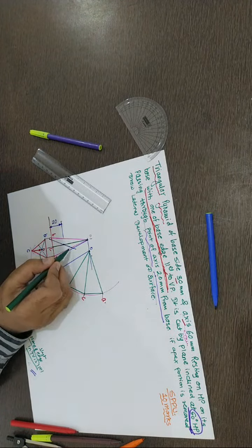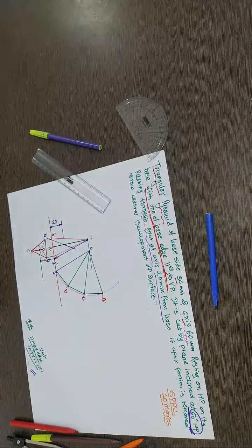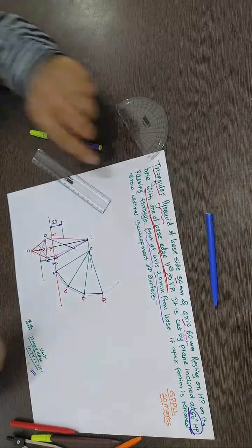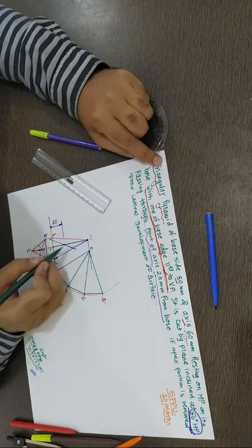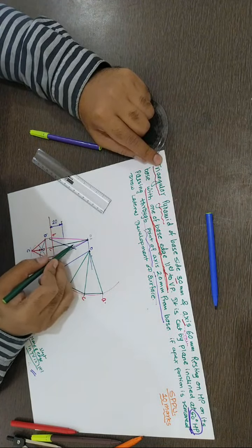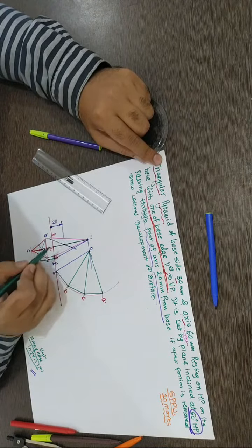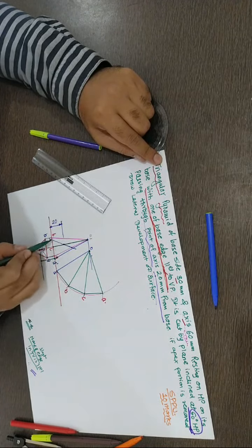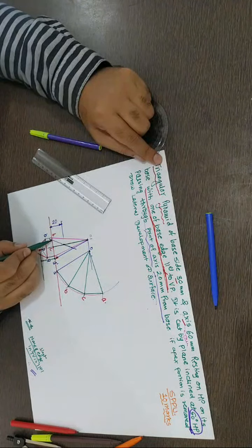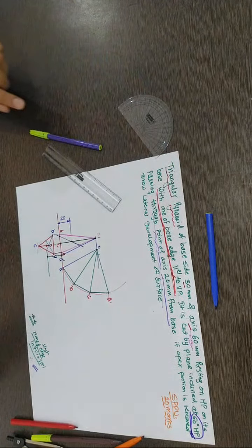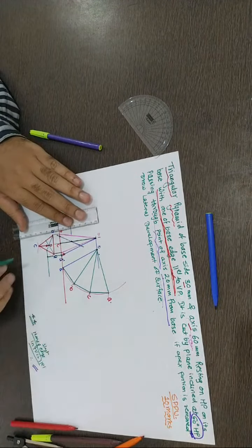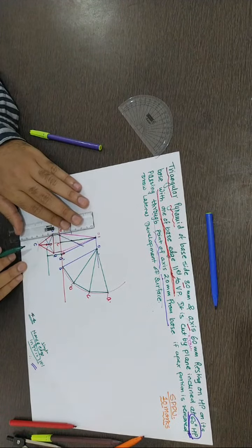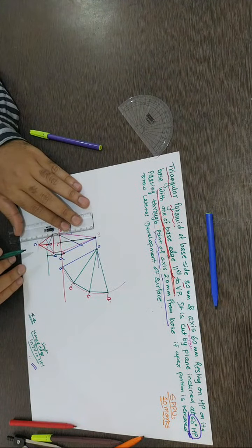Now this intersection has to be transferred. As we have taken this true length, we have drawn the development already. Now this intersection of this OA with the cutting plane gives one point, and with C, another point. We don't have a B, but we have this additional base compared to the previous problem. So see, it's not that simple, but when you read a question, it looks simple.